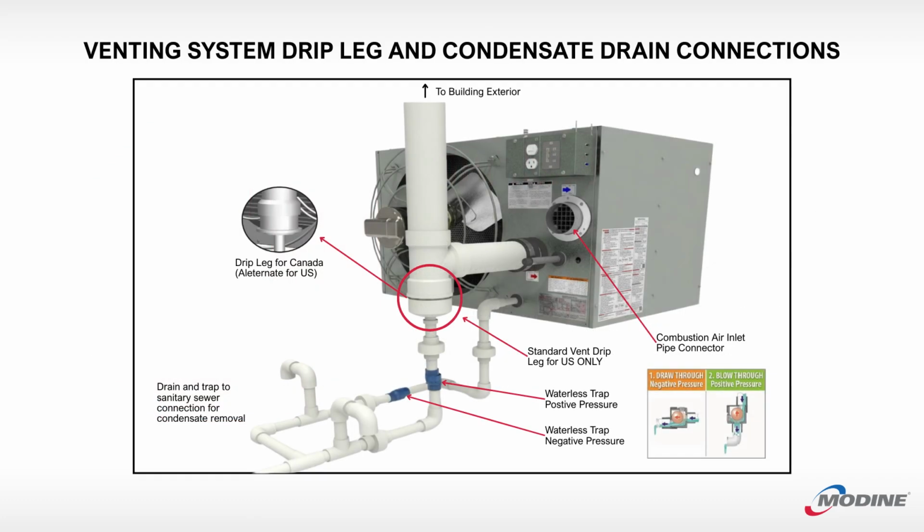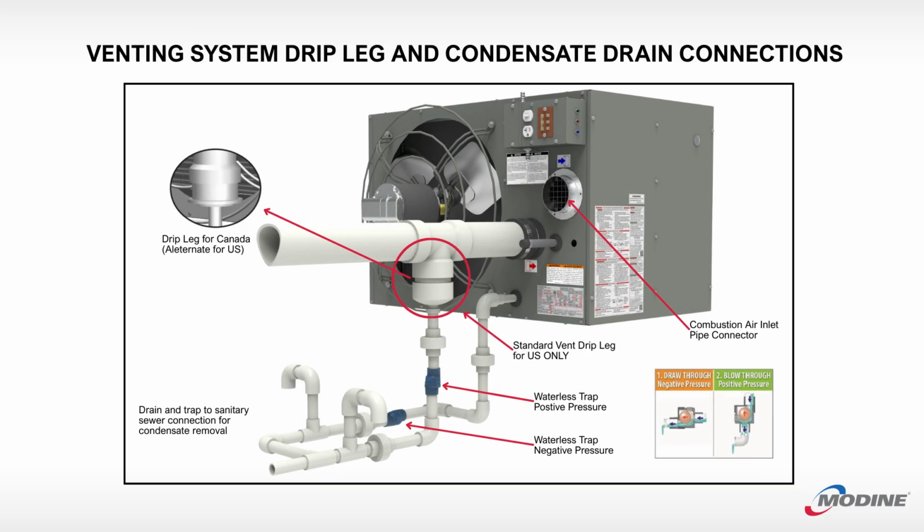During operation of a high-efficiency gas-fired unit heater like the Modine PTC and BTC, condensate is produced both in the heater and the venting system. Proper installation requires condensate drain systems, including proper traps, from the secondary heat exchanger and from the vent pipe.